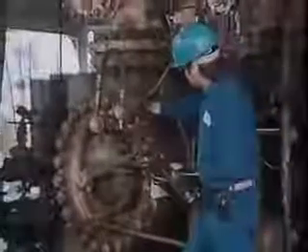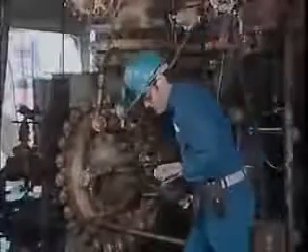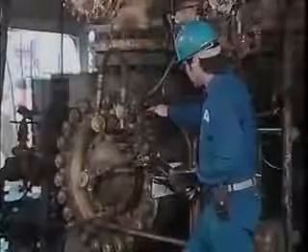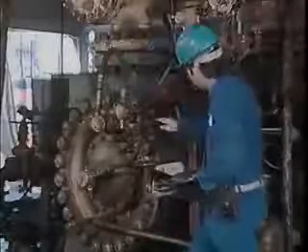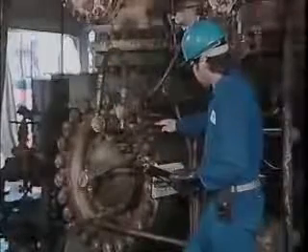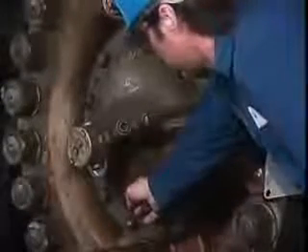An important part of checking an operating compressor is listening for unusual sounds. Most compressors produce a high-pitched hum when they're running. An unusual raspy or squealing sound can indicate a problem with a bearing. It's also important to check the compressor's bearings for excessive vibration and overheating. These symptoms can indicate a possible bearing failure.